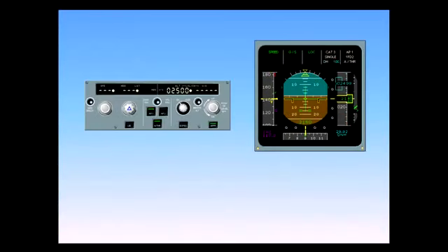The auto land procedure recommends that both autopilots be engaged to ensure the best level of redundancy for auto lands, auto rollouts, or low-altitude go-arounds. However, an auto land can be performed with just one autopilot. Once cleared for an approach, the pilot presses the APPR, or approach push button, to arm the localizer and glide slope modes. The second autopilot may then be engaged.